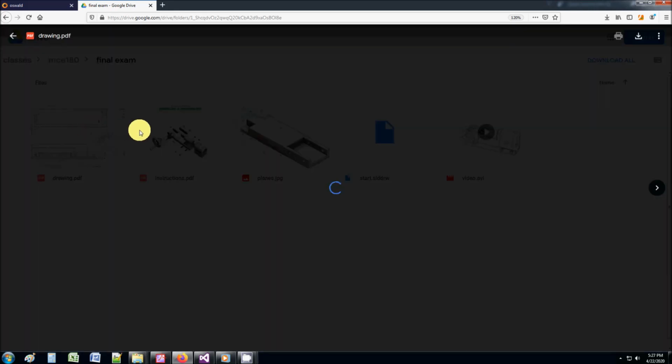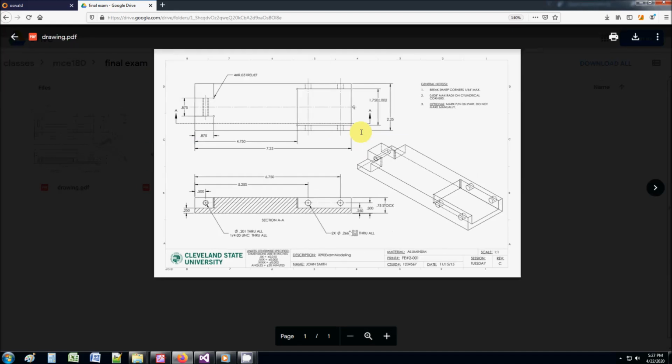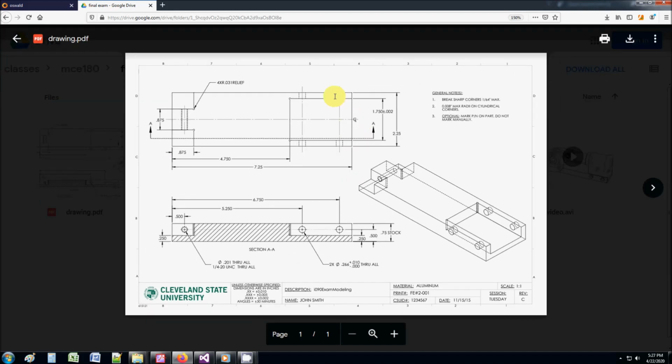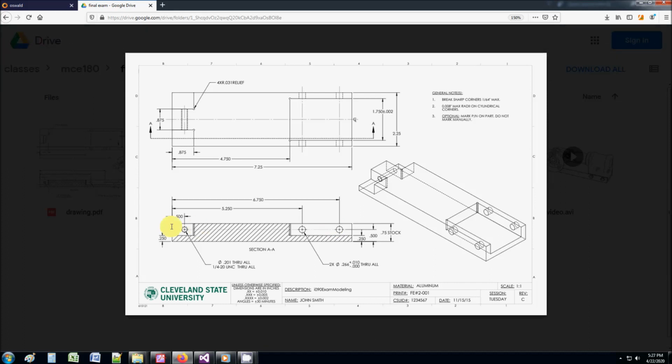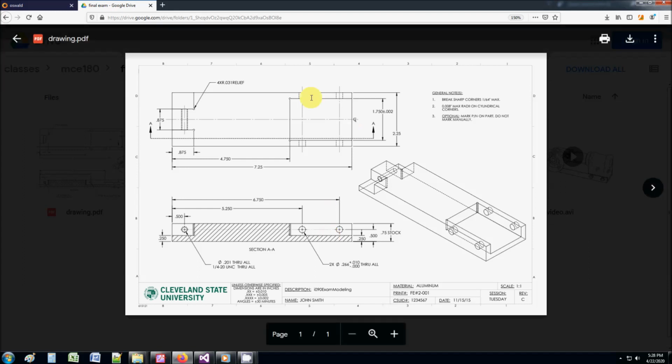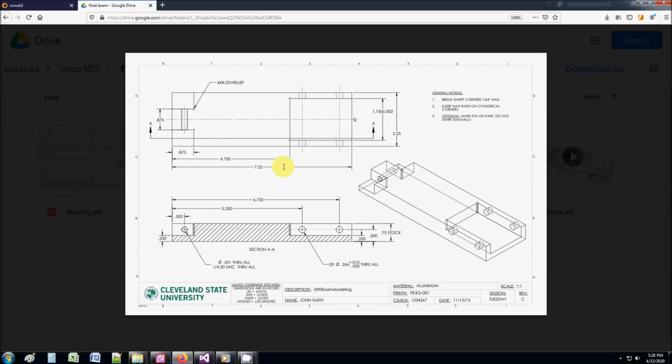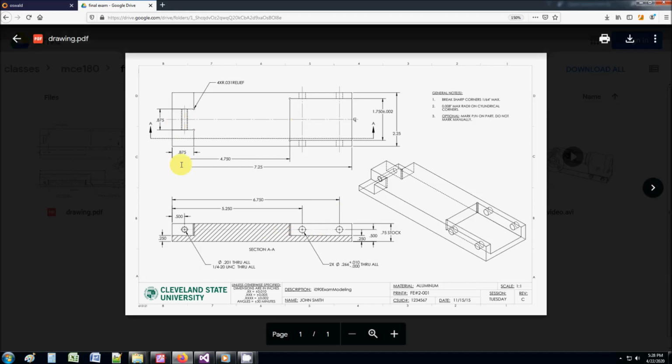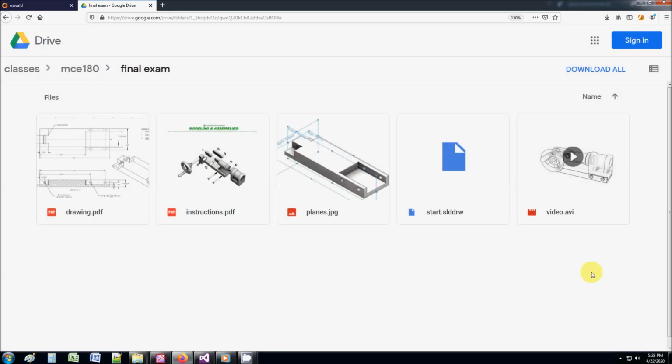First, you open this drawing and you model this object. Again, I'm going to show you how to do that in just a second, but for now, understand what you've got to do. You've got to read these dimensions and build it, just like we learned with the Features 1 and 2 exercise, or homework 4. You read the dimensions, do your extrusions, use the hole wizard and build this. After you have a model, it's going to be an SLDPRT.